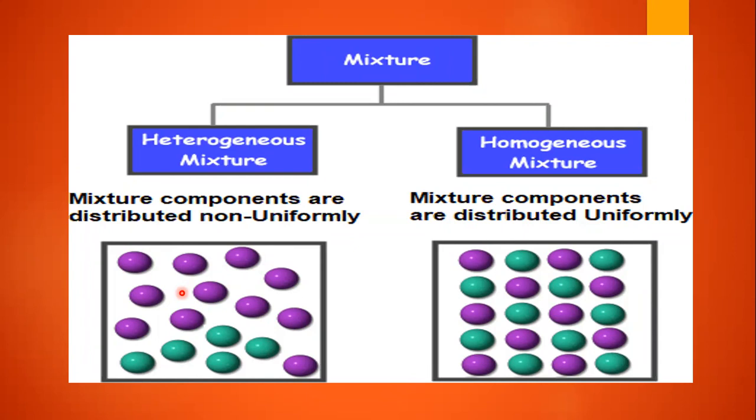If pressure and temperature increase, automatically the density also increases. If we have more density, more dispersion is going to be done. If we have less density, the dispersion is not going to be proper. If we have more density, the fuel which is injected at the end of the compression stroke is going to mix well with this air.